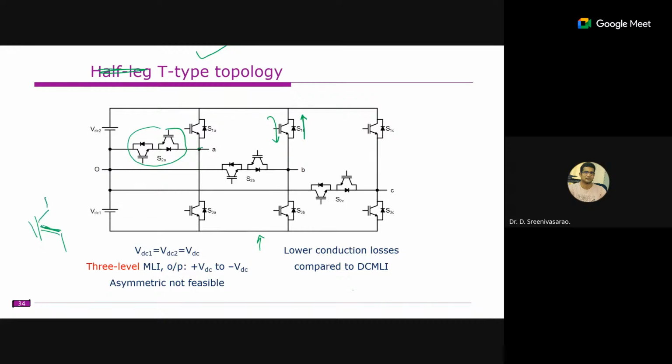So there is some extra line here for the IGBT, the same IGBT symbol, but we have some extra line like this. So this is the IGBT symbol, right? We have some extra line here. That extra line represents the bidirectional property, the bidirectional voltage blocking property.